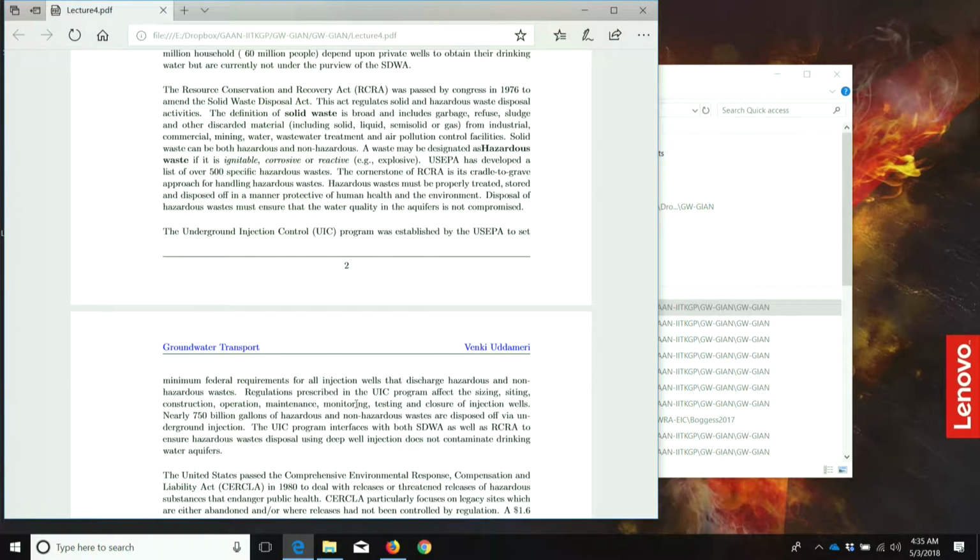Incineration is a possibility. Again, if the disposal, you still have to store it for a certain while before you incinerate it. The big loss of incineration are mostly air quality loss because you're polluting the atmosphere. But if you do store, you have to store it in certain ways to make sure that it's protective of groundwater. So RCRA basically has some guidelines on how this hazardous waste should be stored: there should be double-lined wall containers, they have to meet certain integrity standards and so on and so forth.